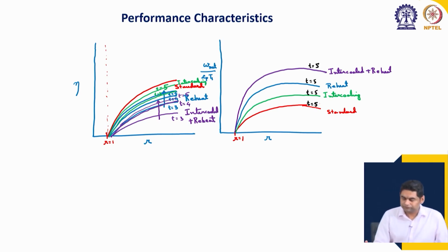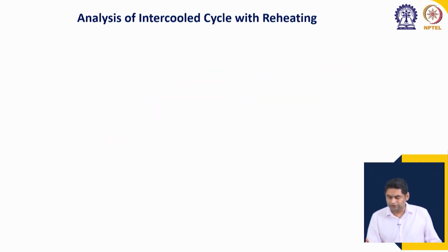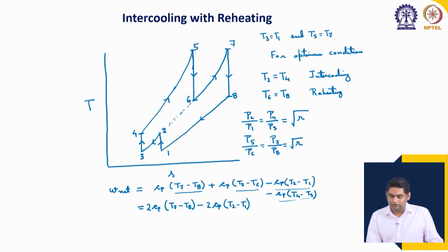Okay. So, by intercooling and reheating we get the highest work output, but the efficiency decreases because of twofold reason. One is that we are adding significant amount of heat in the secondary combustion, plus we also have to use up more of the turbine work output for running the compressor, so we have to add more heat after the intercooling process.